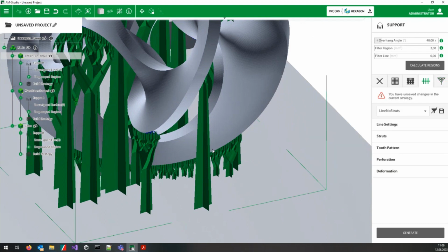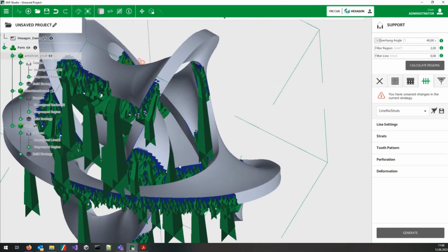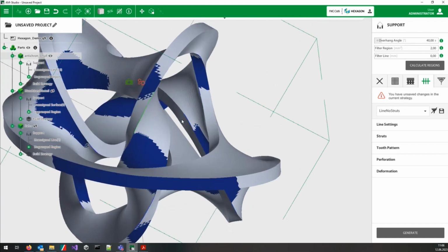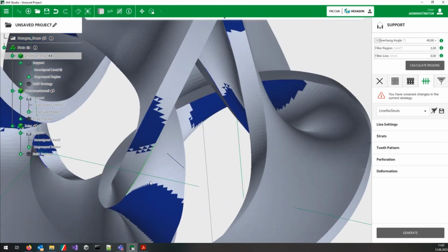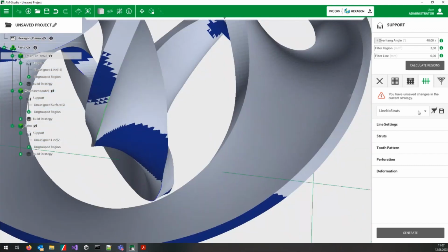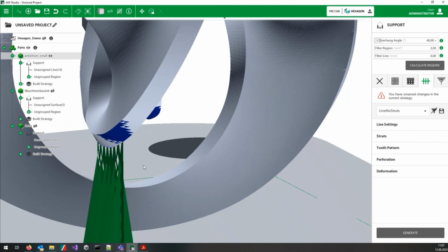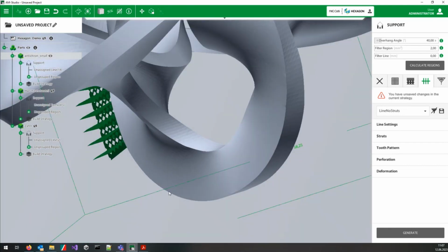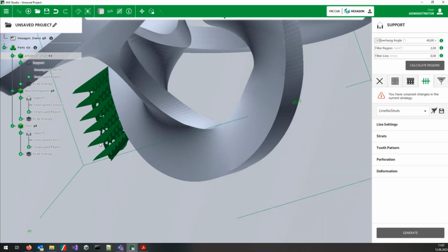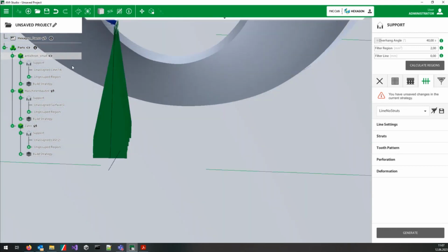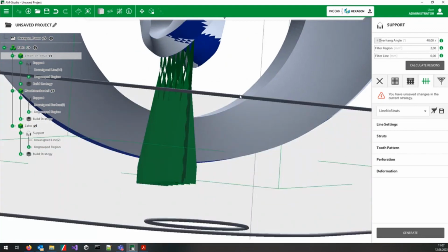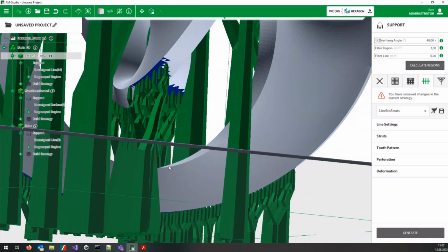Okay, and last but not least, we have the line support. So I have to search for a line. Here it is. So here we have a line or an edge. You can just put a line support underneath. It's just a single wall with so-called struts, the 90-degree triangle-shaped support structures, combined with that just to have a good connection.